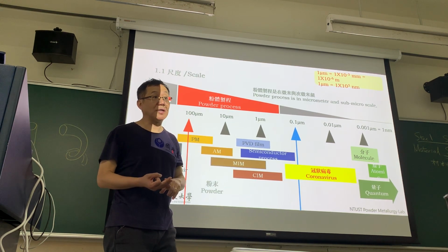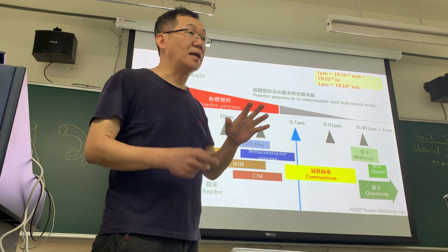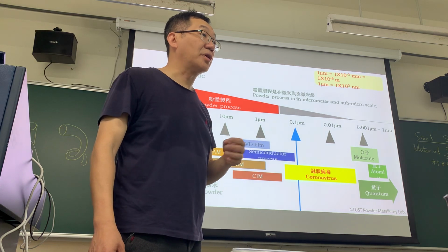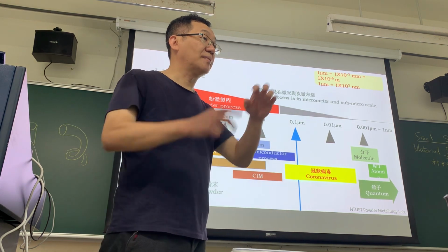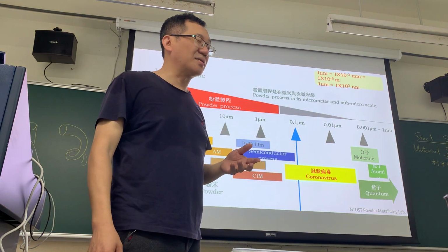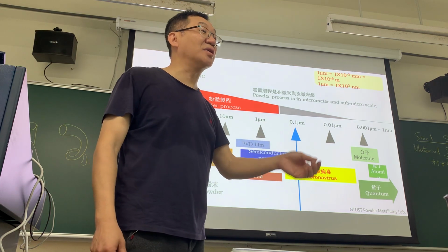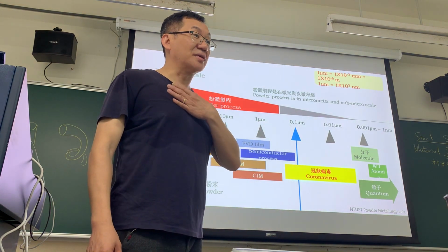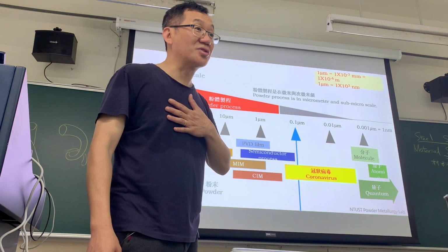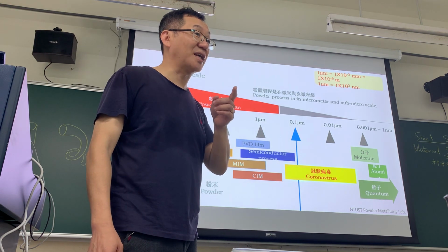Why more dangerous? Because when powder is small, it can fly. Every small powder, if it can burn, will explode in air. So very dangerous. On the other hand, for example, an oxide that is small is not so dangerous, but when it goes into your system, you will get sick. So everything should be remembered. The small size is so dangerous, it should be controlled.